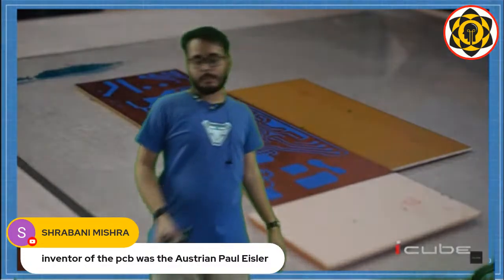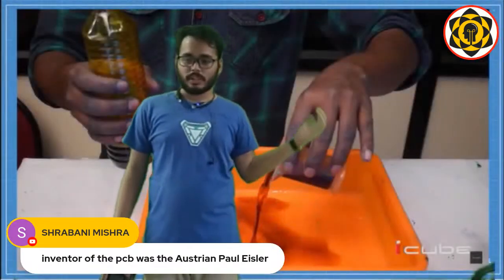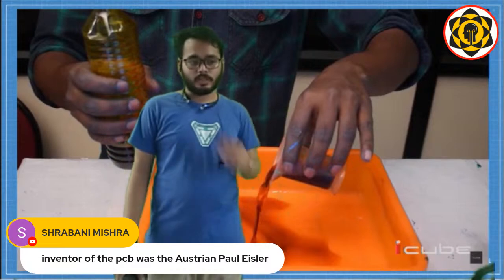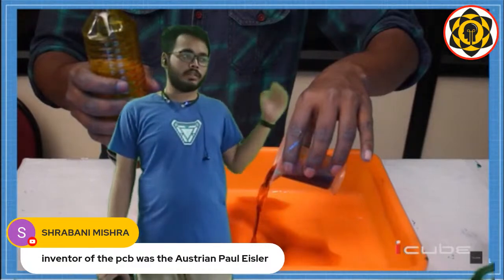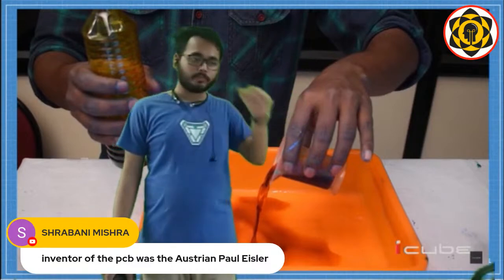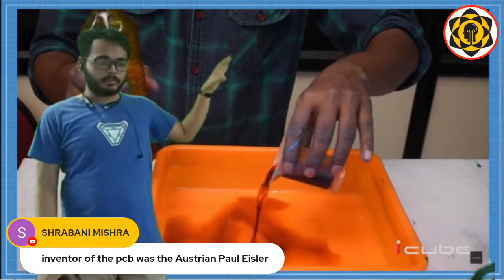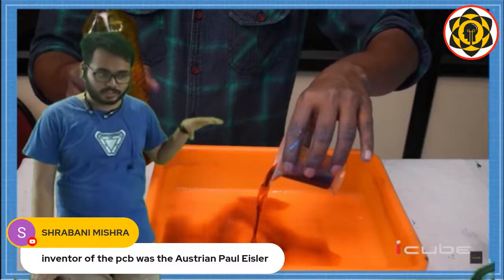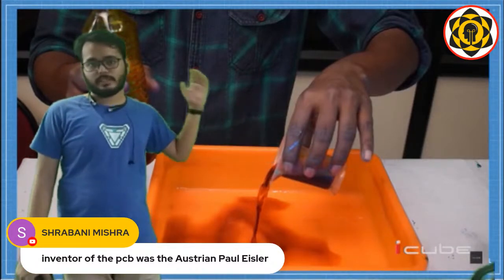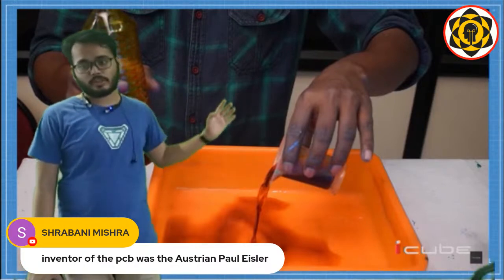For that purpose, we will use a ferric chloride and water solution. We're going to mix once again a 1:1 solution of ferric chloride and water, and then we are also going to add that catalyst. We're going to make a mixture of these things and place it in a tray. In this step, this guy is obviously doing it with bare hands. Please wear a glove. It's very toxic. Please wear a glove.